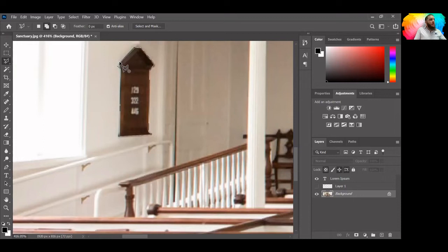Now, let's say I want to close it. So I can either click the start of my line, and you can see how my cursor changed and gave me the circle that's showing me it's going to close the loop. Another solution is simply double clicking on the last point I'm interested in. So double clicking will draw a straight line from wherever you double click to the start of your loop and close that loop to make your selection.